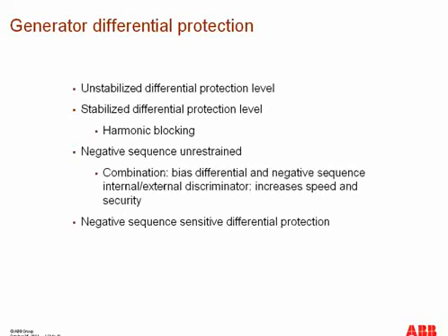There are four sub-functions of differential protection. The first one is the unstabilized differential protection level. So for the very, very high stator faults, we will use this unstabilized differential protection level, and the protection will give out the trip signal without any regard to the stabilizing quantity.